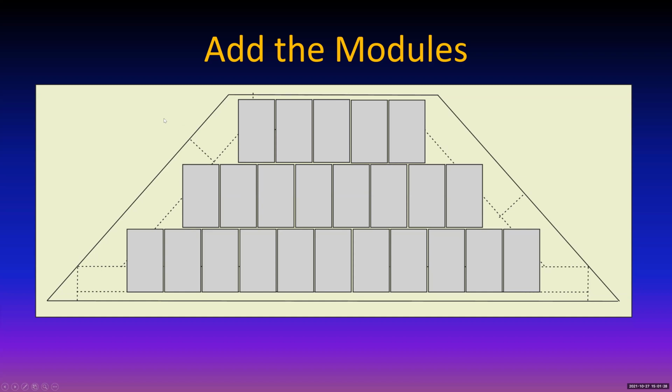Okay, so here we've got an array. Generally, you stay away from the edges. You want to generally stay on the bottom edge. For example, you want to stay 10 inches away if you can, because there's a penalty if you get closer. The wind tends to lift up underneath that, and the wind pressure is significantly more. So when you see modules on a roof where they're overhanging the top or the bottom, well, they will stay there until a nasty wind comes along, and then there's a little bit of chance that there will be a problem.